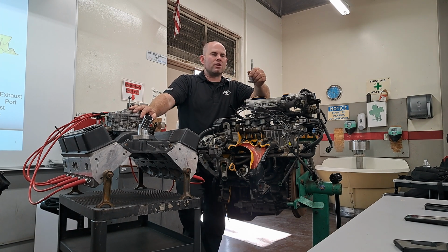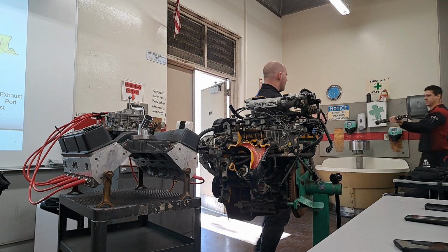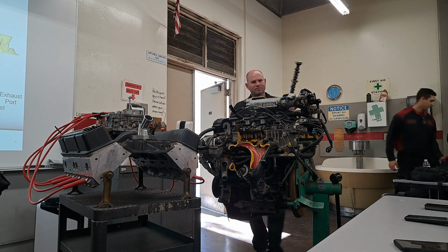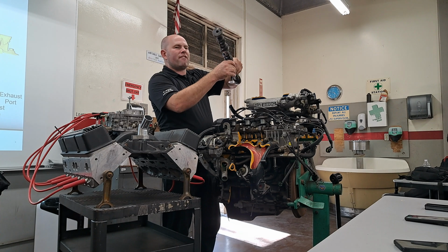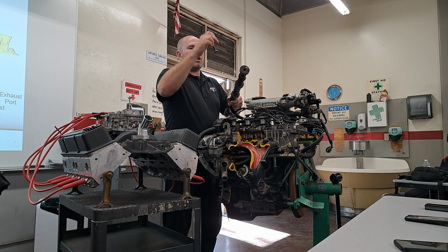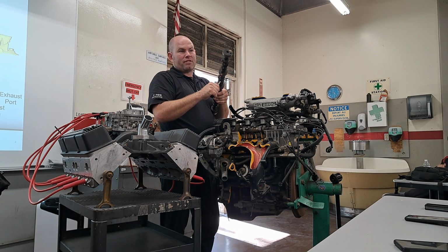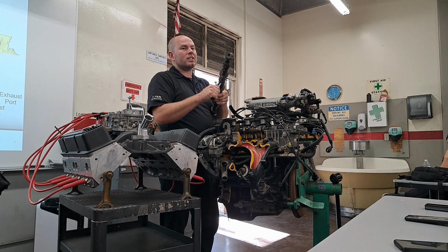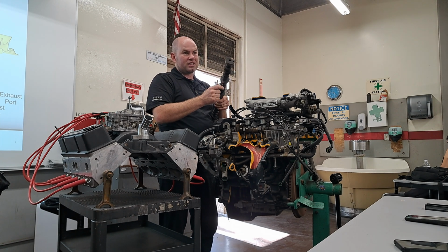Technically, valve float is any time the cam pulls away really fast and the valve is getting pulled up, but the valve is no longer pushing up against the cam. Right? If there's no longer a direct connection, that valve is kind of floating, with the spring pulling it back up. Makes sense? A little scary.